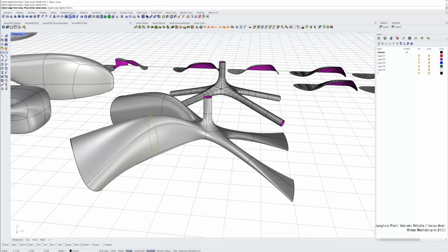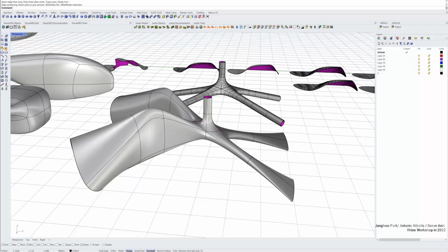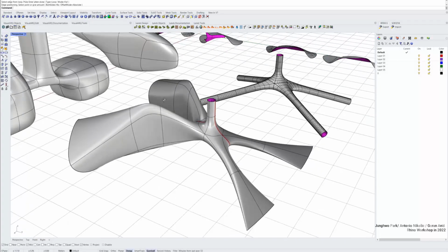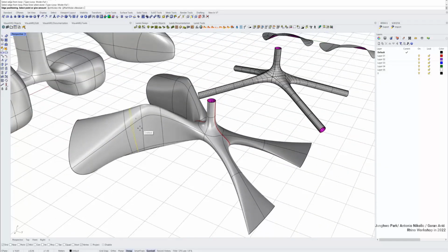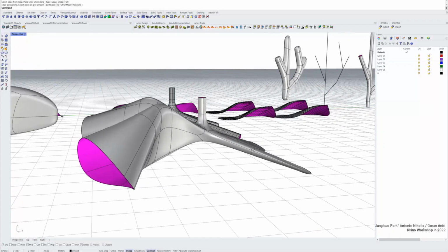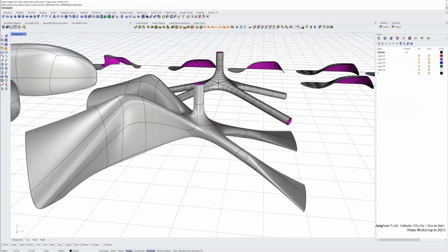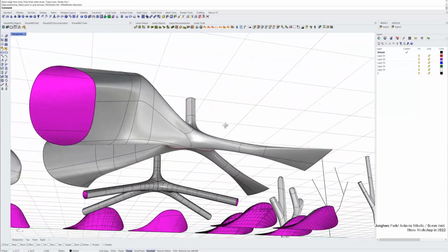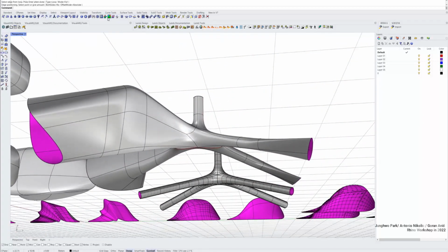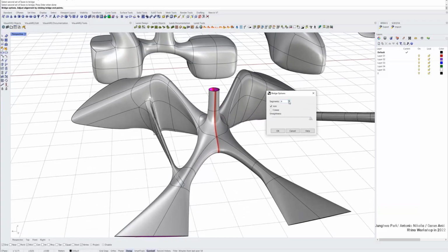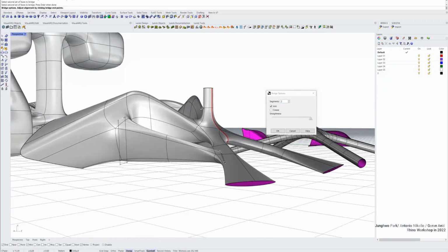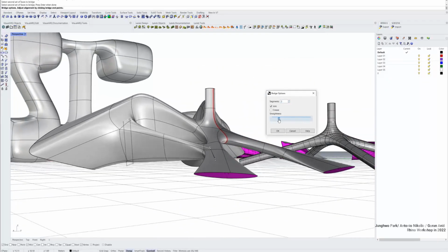I can add a bit of roof here, and you see when I add roof, the opposite side is also added. And I'll maybe move another one here and a horizontal one here, and then we can probably add another one here, and I'll probably bridge this first face and second face, and we can control the number, maybe too many, reduce, and smoothness we can control.